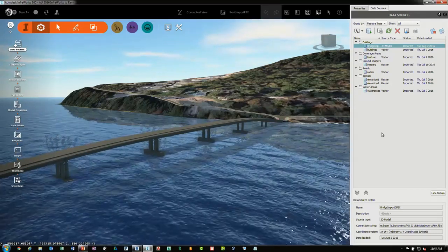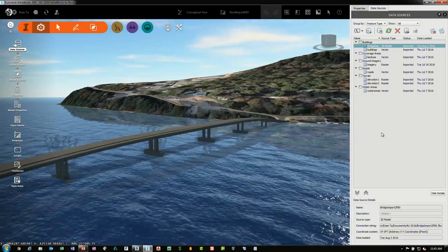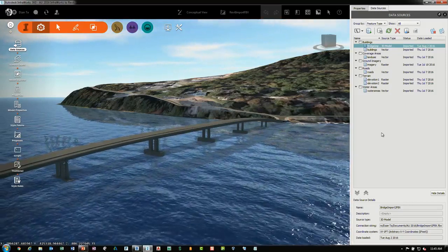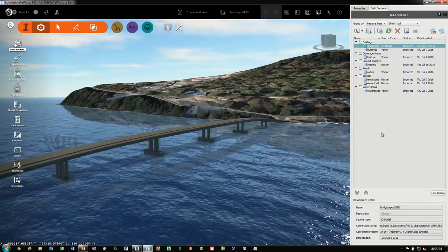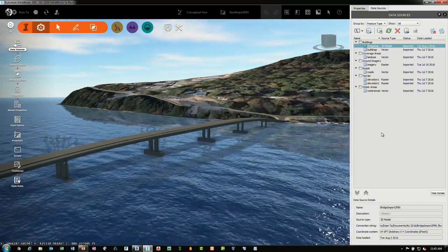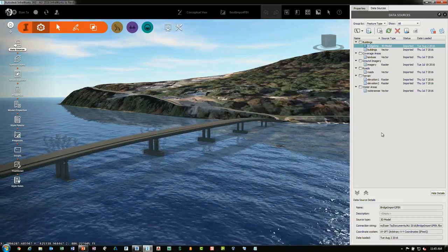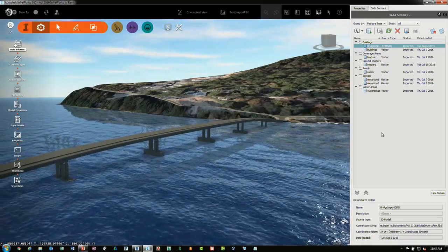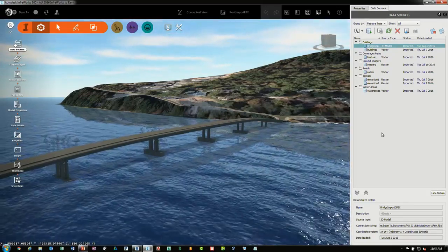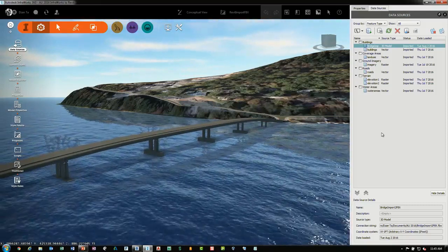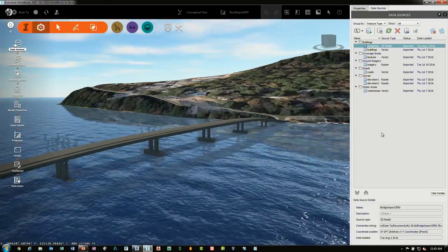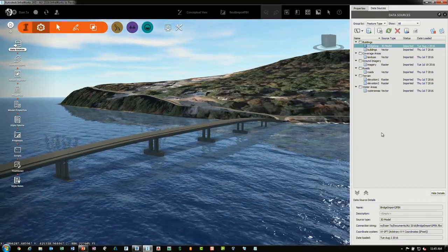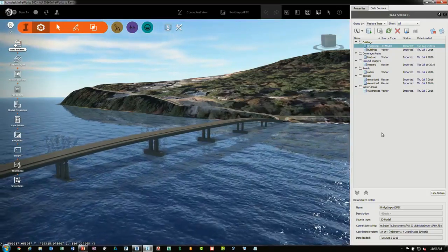As far as I understand, you probably want to do the design work inside Revit and bring it into InfraWorks. I don't think InfraWorks is meant to do that level of design. Positioning, yes. Positioning is a given. So as far as I understand, the context of InfraWorks is not meant for you to go to that level of detail and design work. It's meant for quick iteration, meant for quick logical placement and orientation, things like that, and to get a general overall sense of what the schematic design is going to look like. You'll have to use other authoring tools to get more granular if you have to. Good. Any other questions?